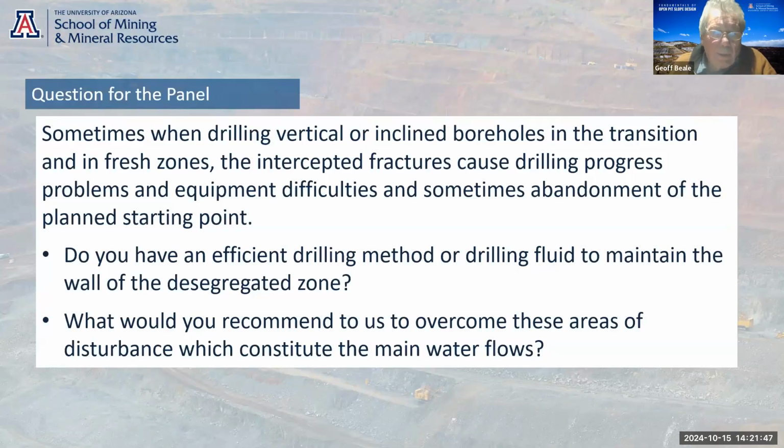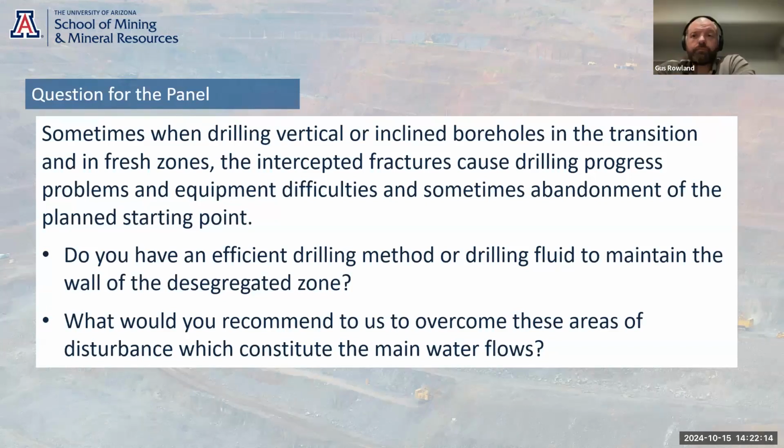So I think for the start, if it's an exploration type program or a groundwater investigation type program, go with reverse circulation. If it's a larger diameter well, there's a reverse circulation drilling method which keeps the fluid low in the hole. But if it's really unstable, you might have to go with casing advance or sonic.